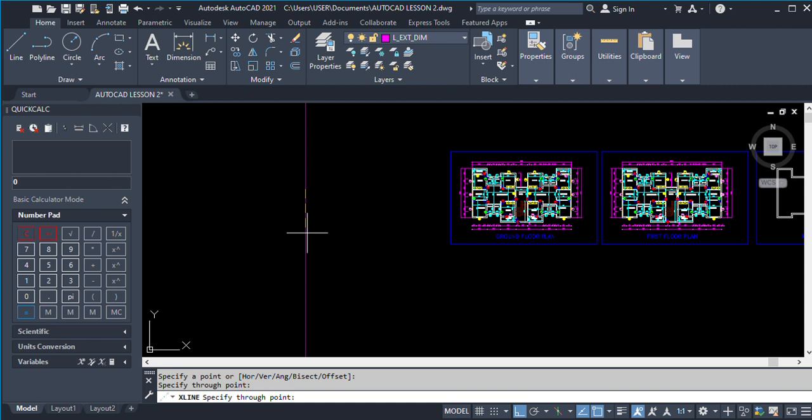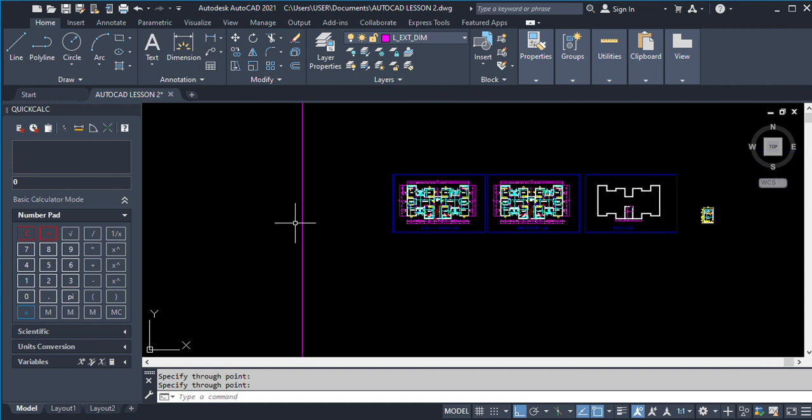Then enter again. I've put the command. I said you must strike the return key twice. Once you type in the command, you strike it. When you apply the command, you strike it. All right, so I have this line now for the vertical side. I'll also have another one for horizontal, so that I will be able to be offsetting it down.